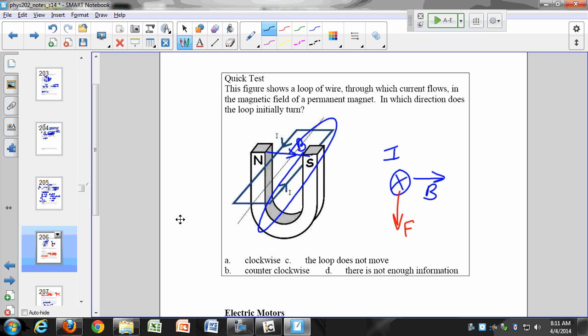If you're looking at the right side, the current's going in, then go up this way. It's going to generate its own magnetic field, right? In fact, that's where that force arises: the current generates a magnetic field, and it interacts with another magnetic field, and that's what causes the force. So you could look at the way the axis goes, but it's easier just to look at the current.